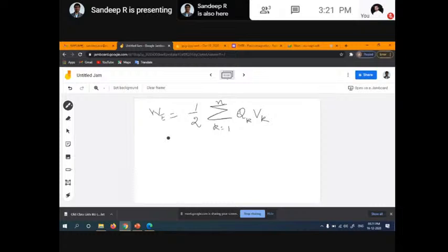And this is for discrete charges, right? Suppose I have a continuous volume charge distribution, then WE is equal to half the volume integral of D dot E dV, which is also equal to, since we know the relationship between D and E, the volume integral of epsilon naught into the magnitude of E squared dV. So this is how you can calculate the electrostatic energy.